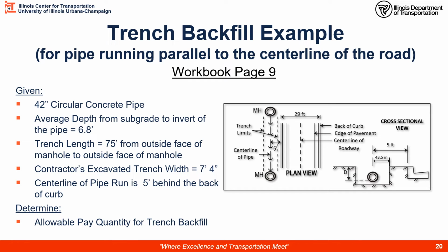Well, the first thing we should do is check to make sure that trench backfill is even required. Because if it's not required, we don't have to pay for it unless the contractor with an extra wide trench encroached upon our 2 feet. Then we would require the contractor to backfill with trench backfill material, but we would not pay for it.